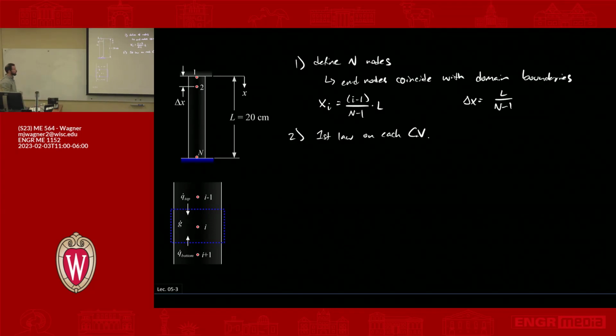All right. So here on the bottom, I have drawn some node I. And in some node I, you draw a control volume around that node. The way to draw it is you're going to have the boundaries of that control volume be halfway between the node that you're trying to model and the adjacent one, right? So you have this width, or length, delta x control volume, but it's centered around the node. So we've drawn that.